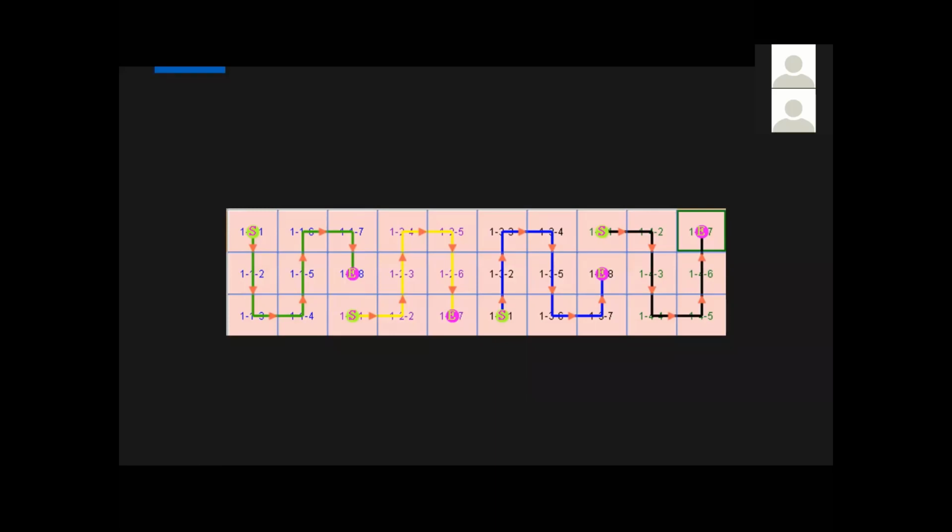But by calculation, the whole screen is within 2.3 million pixels, so there should be a way to make it work with the 660. This is one of the right ways we can configure the wall. Port 1 has 8 panels, port 2 has another 8, port 3 has another 8, and we have 6 panels left, which we put on port 4. Now every port is within 650,000 pixels, and all 4 ports in total, the resolution of the whole screen, are within 2.3 million pixels.